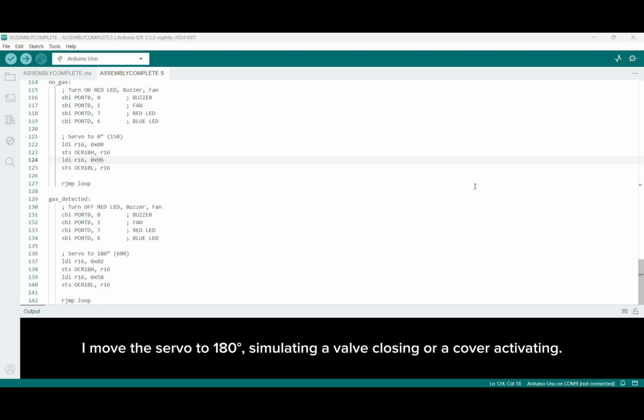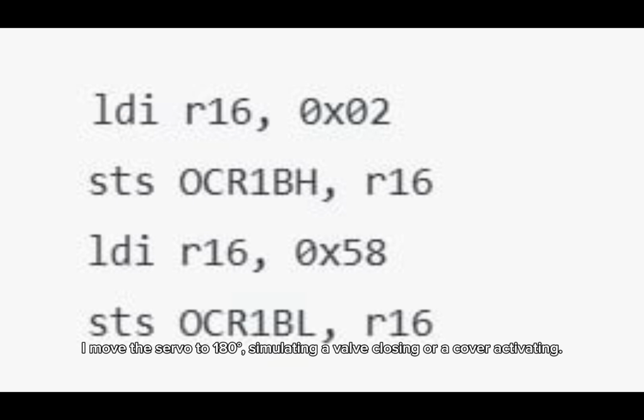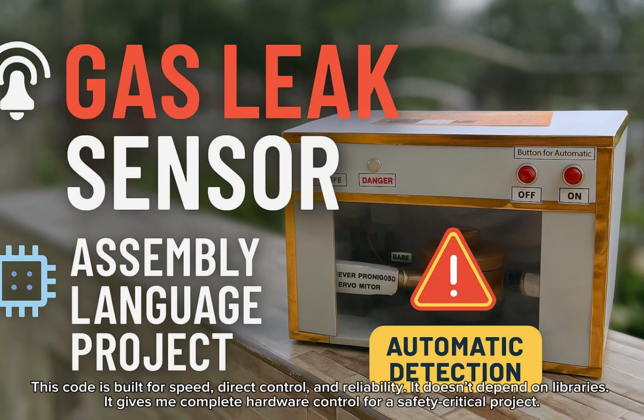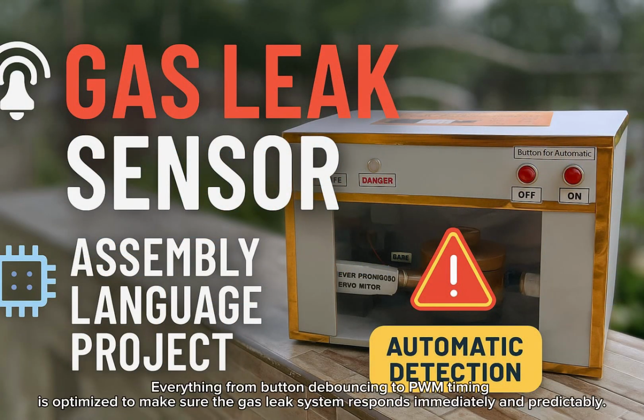I move the servo to 180, simulating a valve closing or a cover activating. Why did I do it this way? This code is built for speed, direct control, and reliability. It doesn't depend on libraries. It gives me complete hardware control for a safety-critical project. Everything from button debouncing to PWM timing is optimized to make sure the gas leak system responds immediately and predictably.